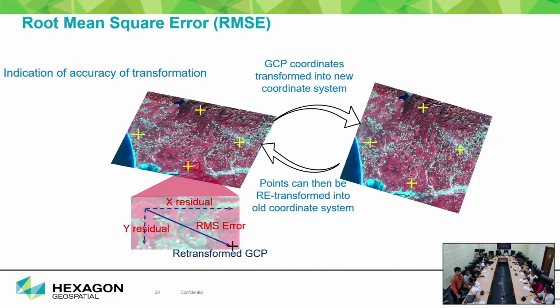Root mean square error arises when you convert your map coordinates to ground coordinates. There will be different types of error due to the algorithm, because we are resampling the data and not converting the exact data. Suppose you give the input as coordinate points, then that image is resampled again.